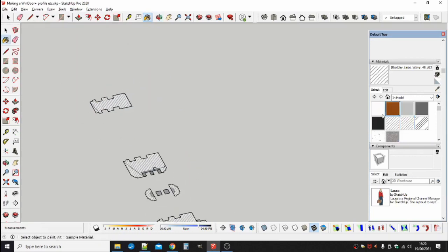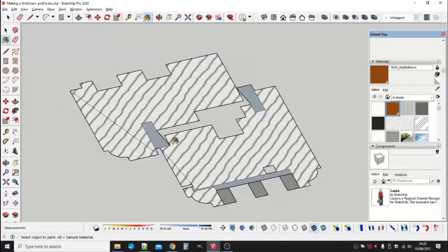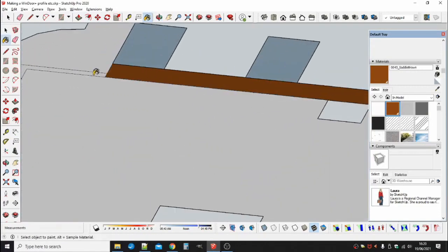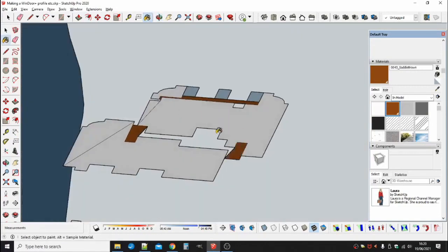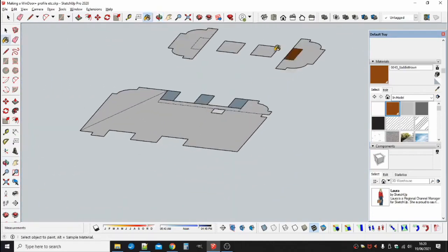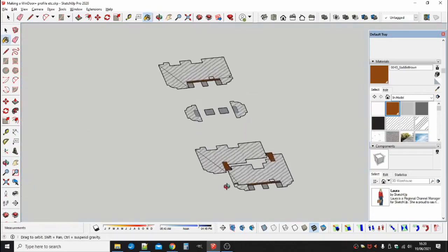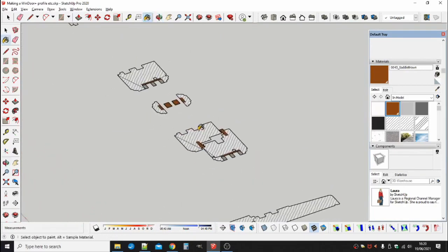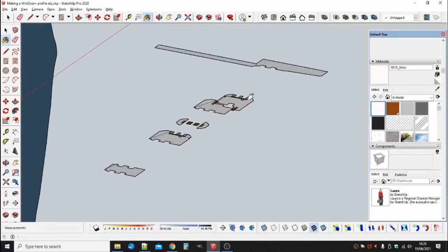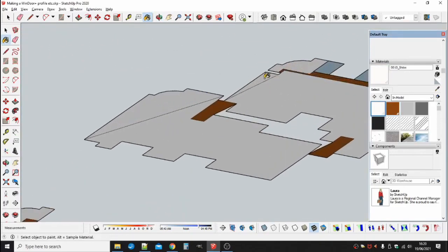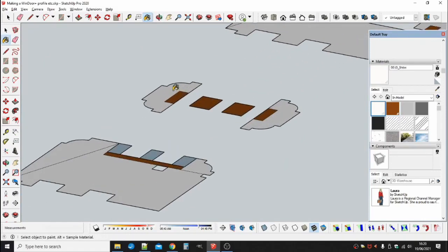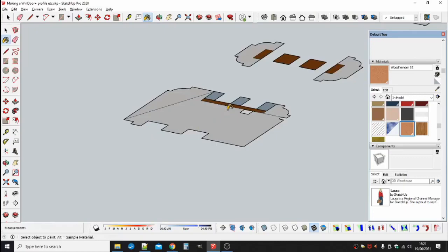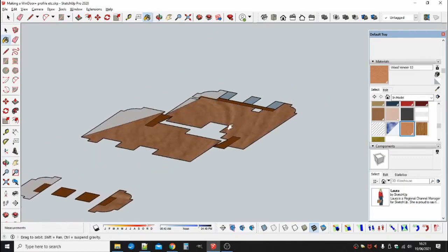Paint the back face of wooden parts an architectural hatch texture for wood. The back face will be the inside of the extruded shape. The back face is always facing up when drawn on the ground plane. This is the correct orientation for WinDoor plus Custom Profile components. If you wish, you can adjust the hatch so that the profiles look more like they are made from separate pieces of wood, although this will not make much difference to the 3D window.